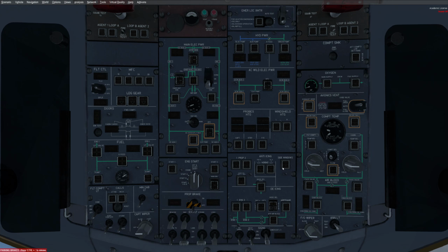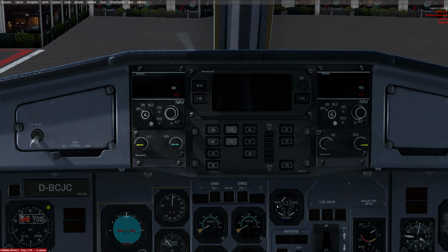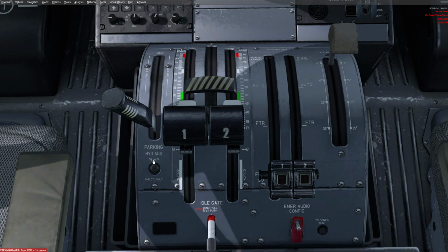Okay, so you've got these 3 crossfeed, don't worry about that. If you wanted to see the gauge involved in all these cases, it's right down here. It's a triple gauge. This is the accumulator pressure for the brakes, blue and green lines. So that just might give us a sense of things. And that button I mentioned below the parking brake, that's right here, hydraulic auxiliary pump. If you were to push this, it's only available for 30 seconds. It's useful for the parking brake hotel mode bit for the prop.